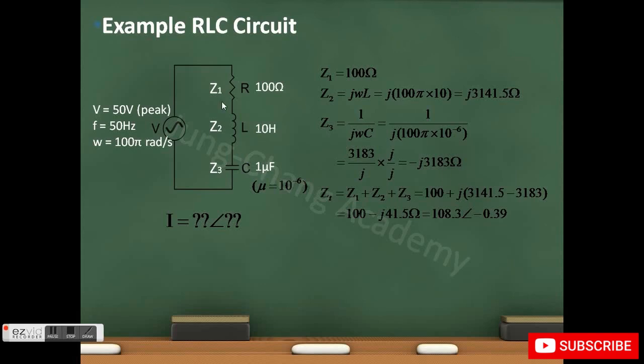Now since we have Z1, Z2 and Z3 in series, we can simply add the impedance up. So you just add the real part and the imaginary part separately. And you know that the Z total, ZT, equals 100 minus j times 41.5 ohms. We can convert this to a polar form, which will give us 108.3 with a phase angle of minus 0.39 radians.